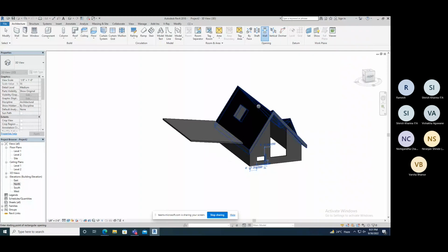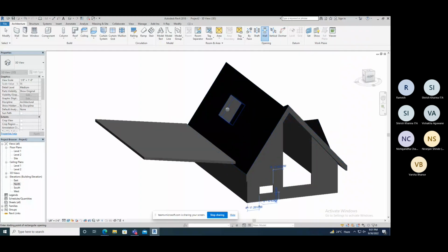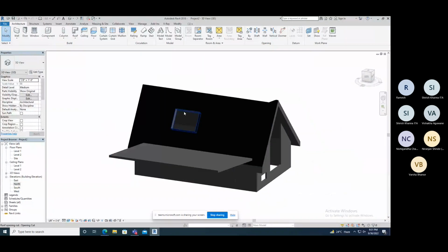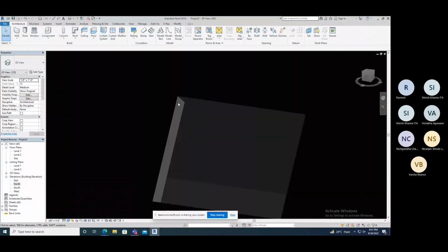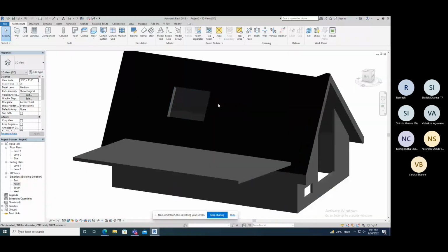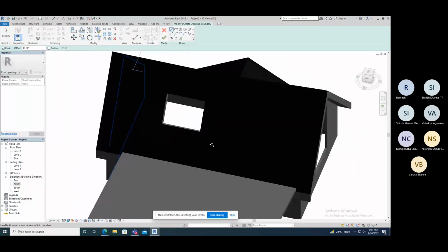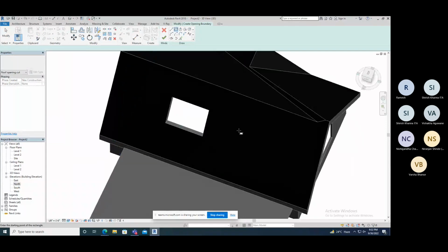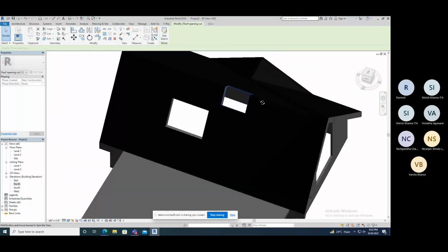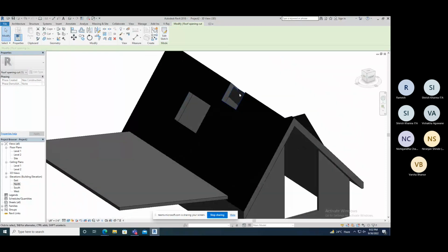Vertical cut is a little bit different from this cut. See, it is perpendicular to the face. You can see it is perpendicular to the face. Now this cut, you can see this edge, it is perpendicular to this face. Now, if you have a straight cut, a vertical cut, go with this. Select your object, and then from the top you can create a rectangle. See, it is vertical. This cut is vertical.